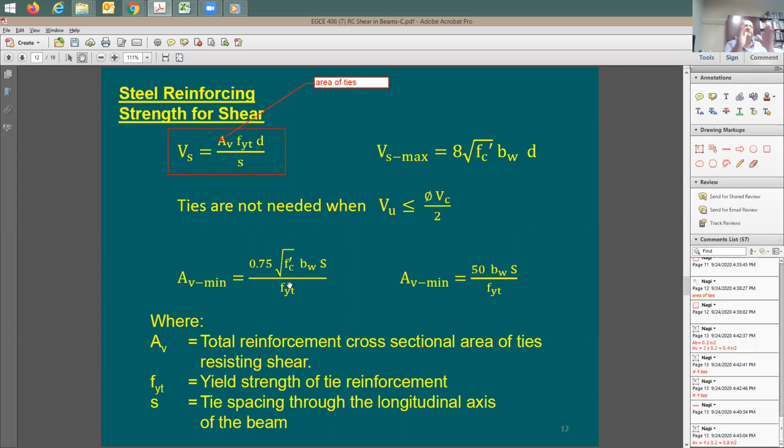Just imagine if you have all the ties 3 inch on center, how would you put your hand inside there to tie them? It's going to be kind of impossible, right? It's going to be very congested. Don't you agree? So you'd like to have some good spacing, maybe a foot, maybe 10 inch, 8 inch is going to be the worst case. This is going to be the smallest. But you'd like to make them as big as possible.